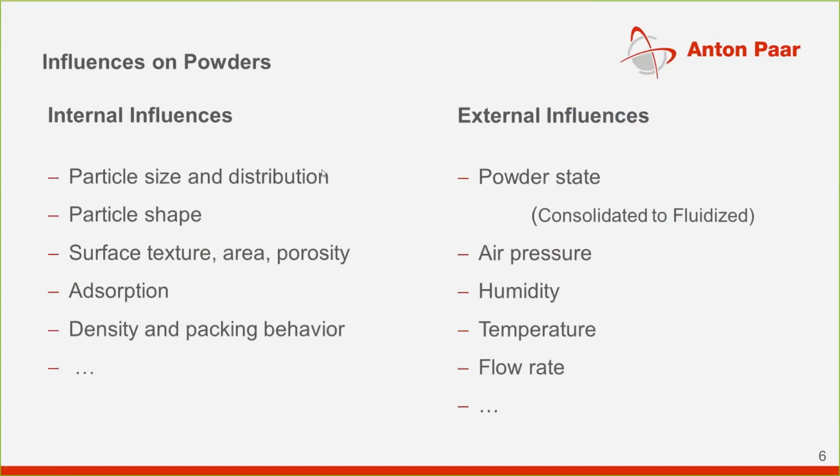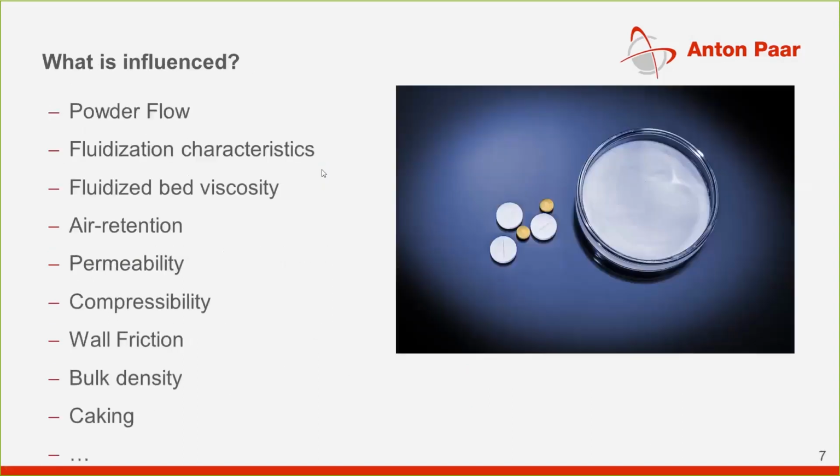So the question, of course, which arises here as well is what parameters of a powder are influenced. Pretty much any property of a powder that you can think of is influenced by this. So the flow will be influenced, the fluidization will be influenced, the permeability will be influenced. For example, if you increase the normal stress, the permeability will drop. The compressibility can depend on how humid or how warm the sample is, and so on.